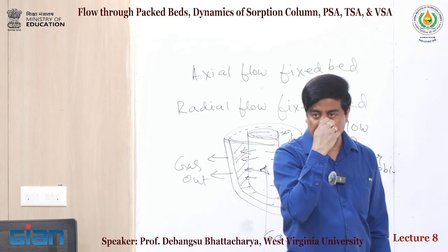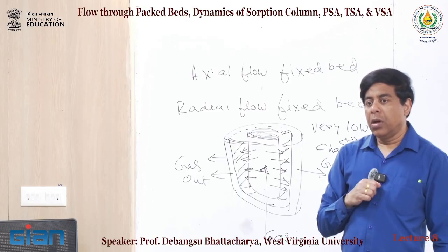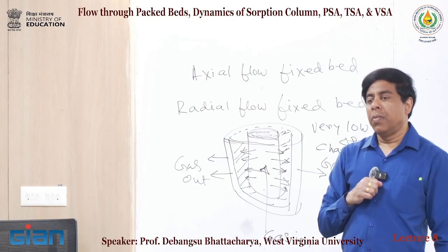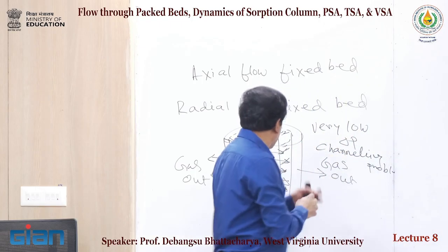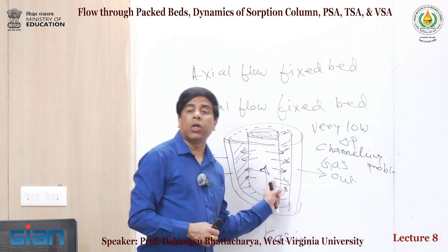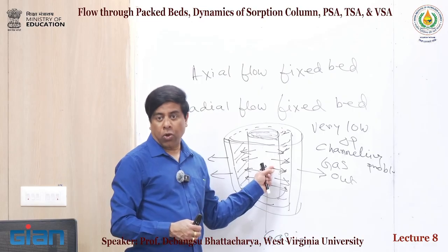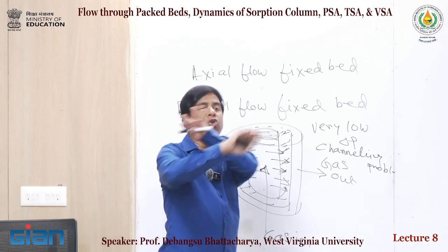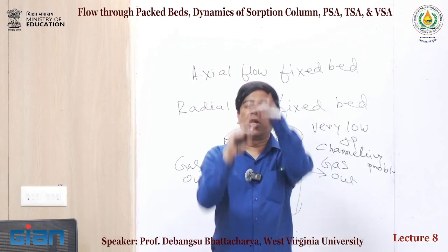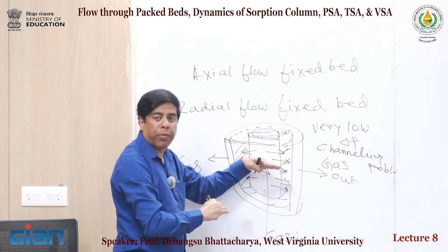Yeah, please. We can have a heat exchanger kind of arrangement, putting baffles backwards and so on to increase the residence time. For these, people do all kinds of designs to ensure that you can reduce the channeling. So it has been done commercially. You could even shroud half of the bed if you are operating at a lower flow rate and all of these things. So you can make it actually a half bed.